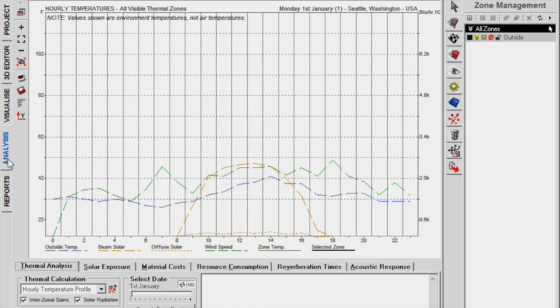It really just depends on what the thermal characteristics are. If there was no wall on this side and it was completely open, we'd track perfectly with the outside weather. But because the walls have some sort of surface with characteristics that slow down the flow, it's not a free flow, you tend to have this lagging behavior. The inside temperature is going to try to match the outside temperature, but it's always going to lag behind a little bit.